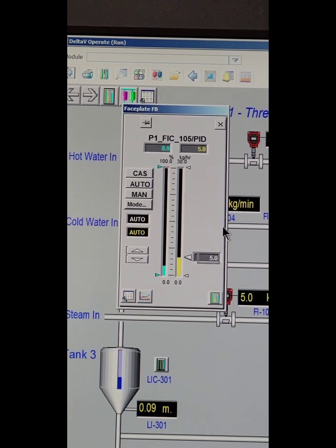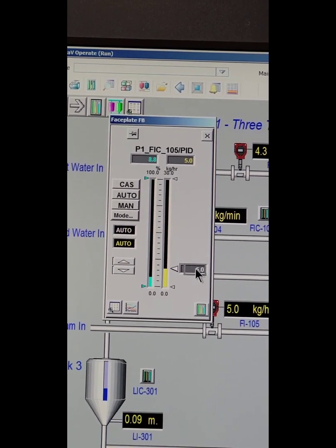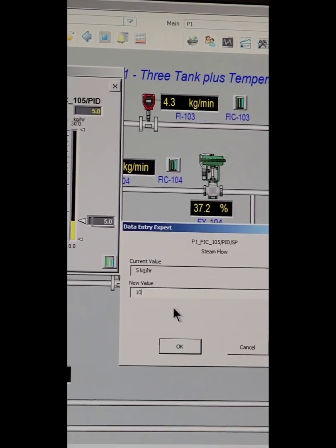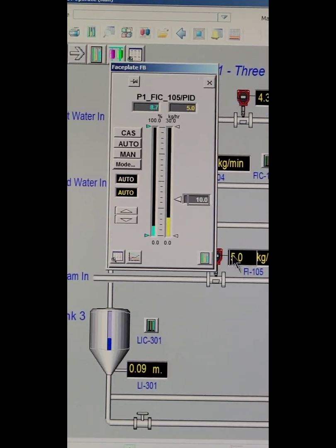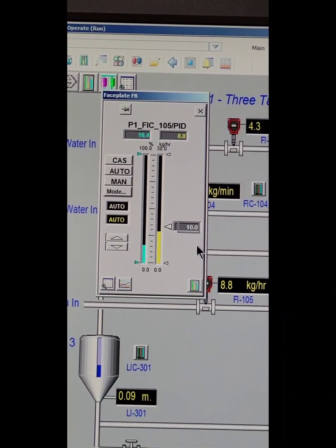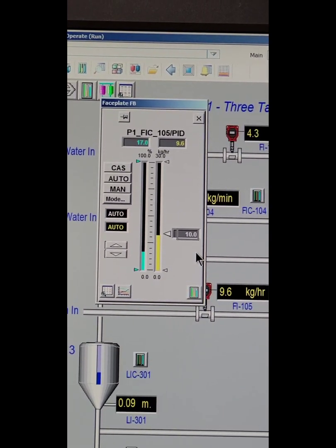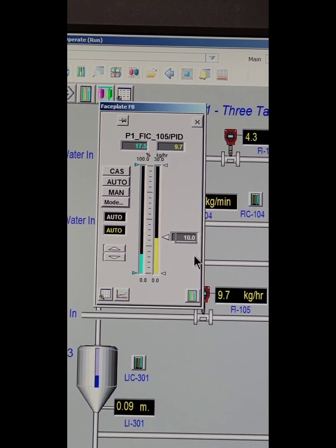And as the last step, we increase the hot steam inlet flow rate by 5. So we will go to 10 for set point. This is the last step of worst case, and after that I will show you how we collect data and how we use it.